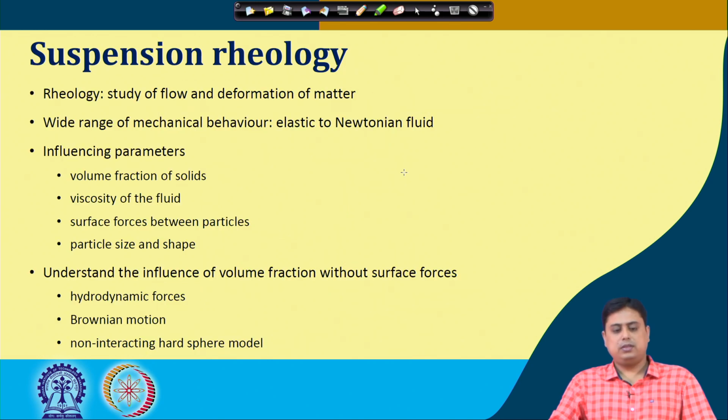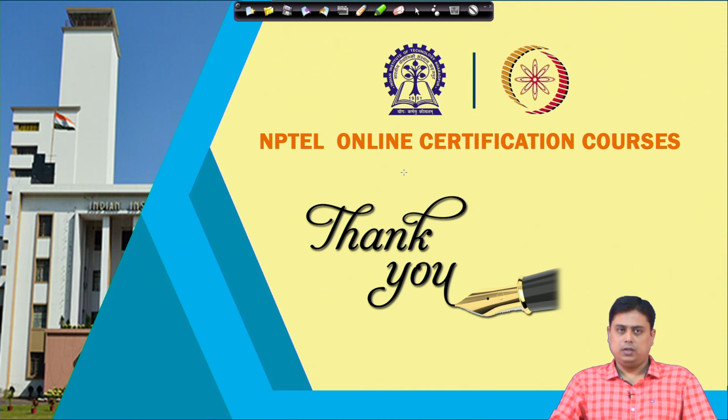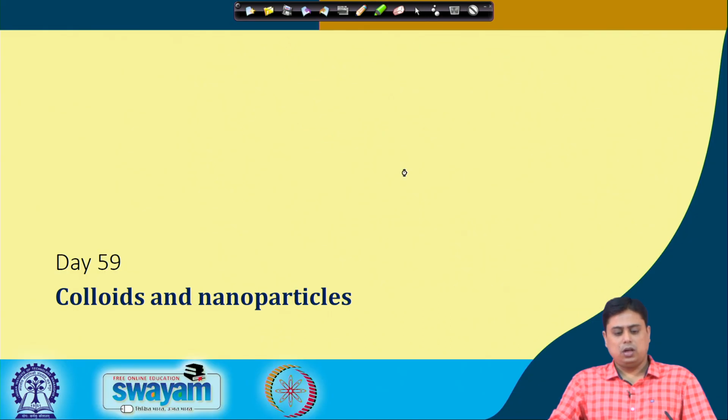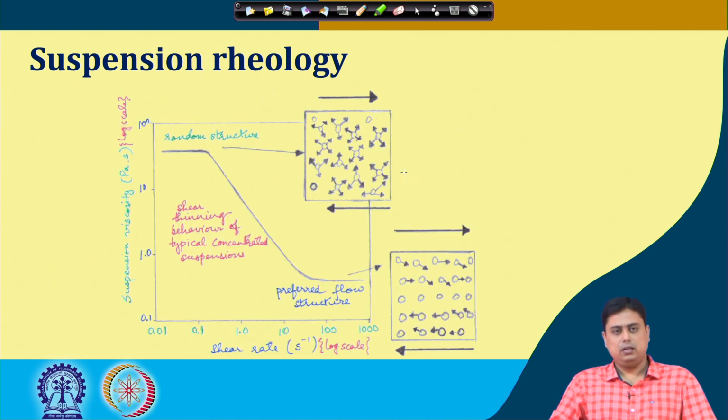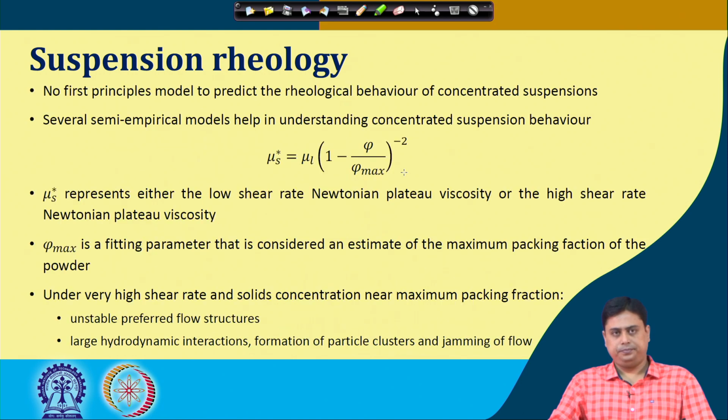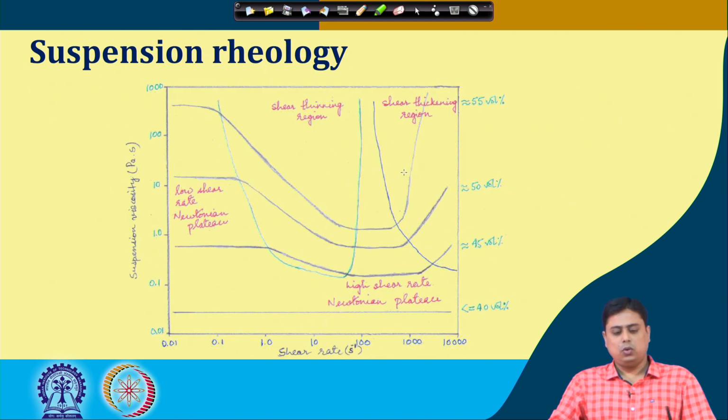and then we have seen the suspension rheology. In the suspension rheology, we have mainly focused on estimating its density and viscosity, and we have understood why the shear thinning or shear thickening mechanism triggers and when is the onset of this trigger. So, we have seen such a phase diagram, and we have discussed this.